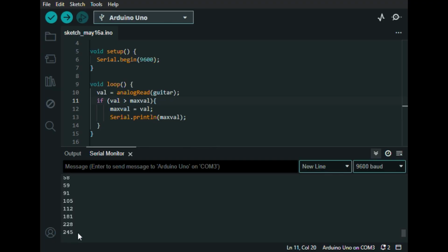Let me just quickly plug it into the 5 volt line. I'm grabbing a jumper cable and I'm putting A0, touching it with my finger. My finger is at 300. And if I plug it into the 5 volt line, yeah, it goes all the way to 1000. Which means our guitar goes to about a volt. And that is actually what we found with the peak detector. Don't remember what we found in the other video, but this is probably a better way to test the guitar voltage. And now we already see our first problem, and that is that we can't read negative voltages.